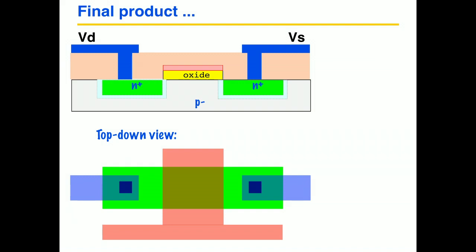Okay. And then if there were more layers of metal, this process can be repeated. We can grow another oxide on top, put some cuts in it to make vias or connections, and then put more metal on, and then pattern that, and kind of keep that process going. And things get bumpier and bumpier, but we can go for some small number of metal layers that way.